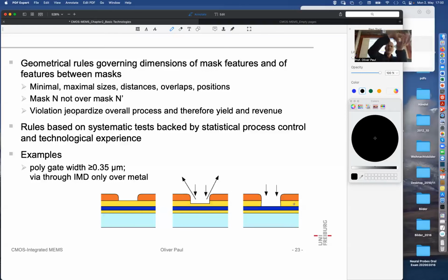If the etching stops on some metal, there may be no longer some kind of species that reflect the fact that the oxide is being etched, because there is no more oxide etching. And so imagine that the plasma color changes, and the guy who looks in the window of the plasma etcher says, now it's over. Let's do 5 seconds of over etch to be sure that it's over everywhere.